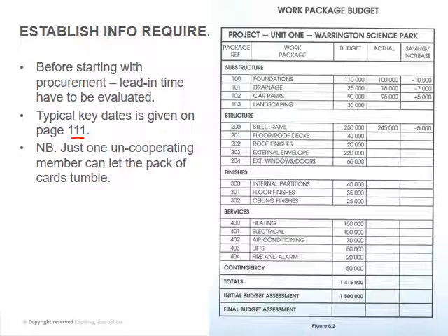So what will happen is, for instance, you've got your subcontractor that's going to look at your foundations. So you've established your budget, and you've established that you're going to remeasure all of the work. You've got some standard rates that you will apply, for instance your excavations and so on, but the quantities aren't final yet. So during the actual work, you measure your actual quantities and you try and show a saving there.